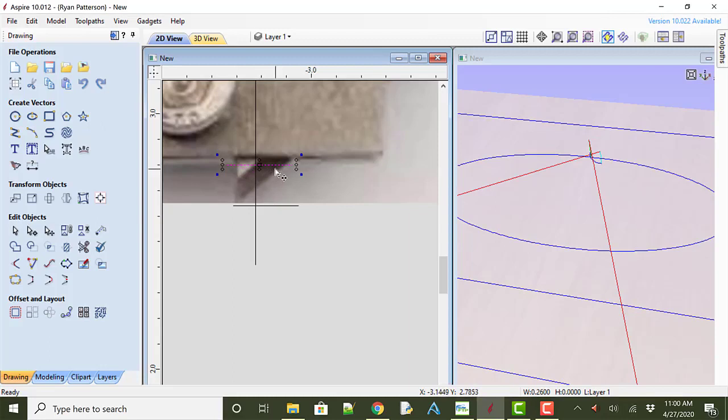As that knife rotates through the material, is there a big enough radius to allow this knife to not bind as it is swooping or cutting around the specified radius? So the deeper you cut into the material or the thicker your material is, the larger this radius would have to be.